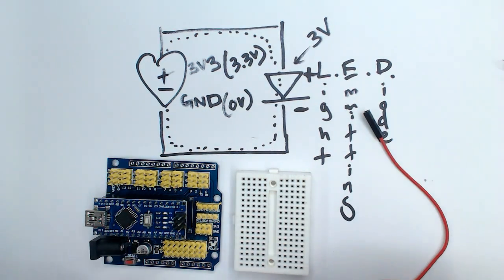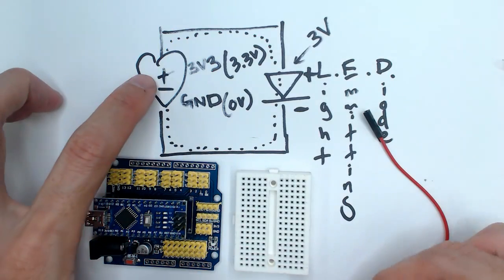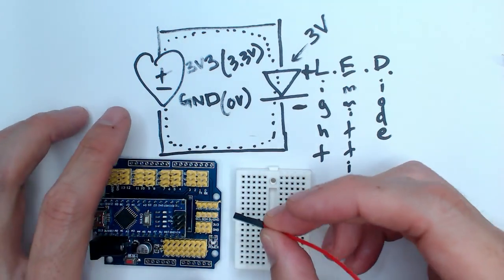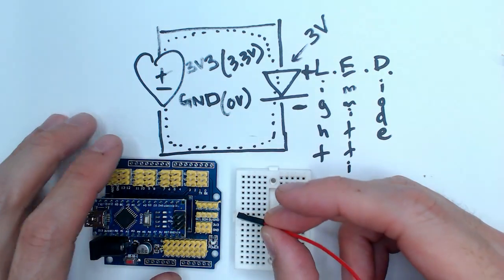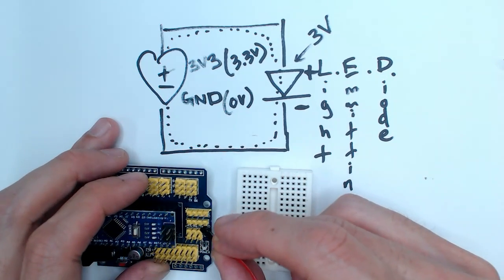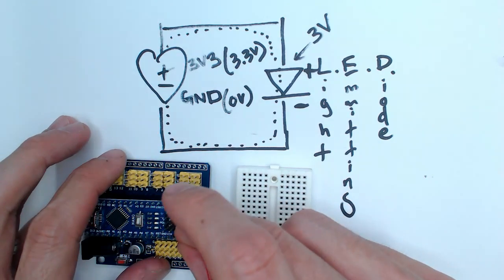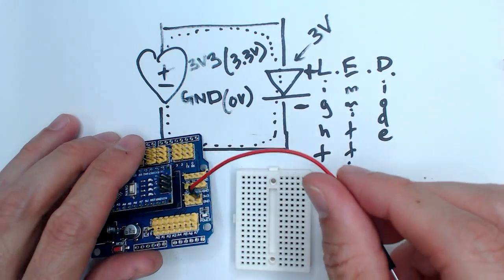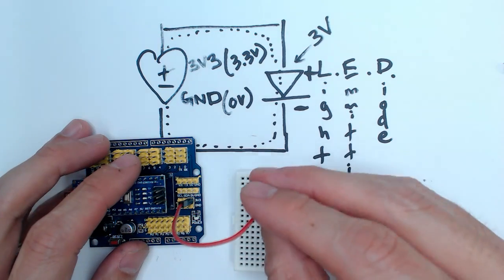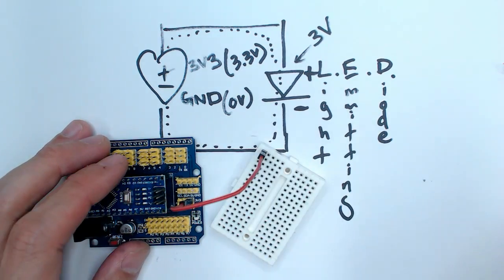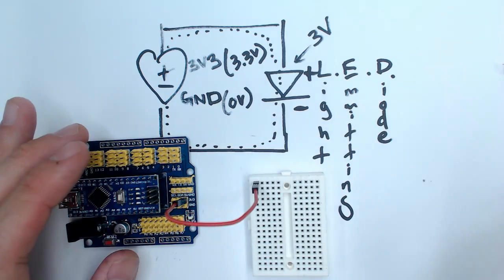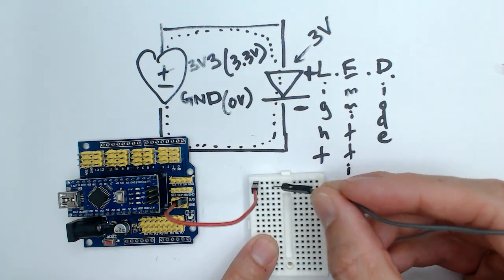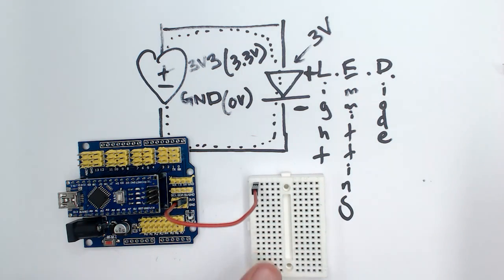All right, so now let's connect the plus to the breadboard. So what we do is we find the plus, which is going to be connected to 3V3. So then we go here and then we plug it in. All right, and it goes right there. Now let's just stick it in the top row here. Boom. All right. So that means this entire top row is 3V3 now.